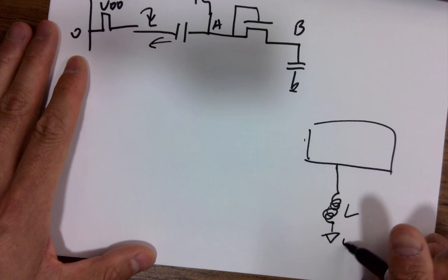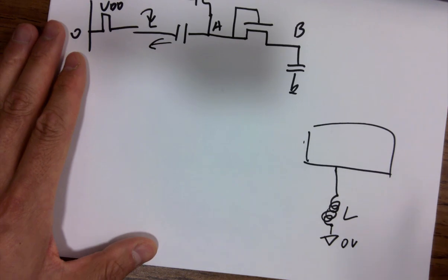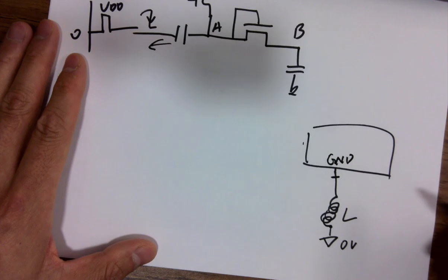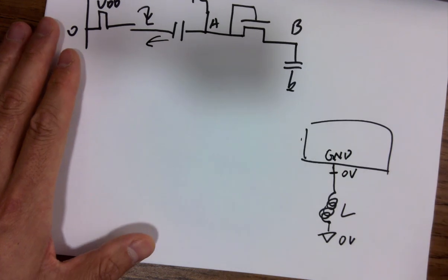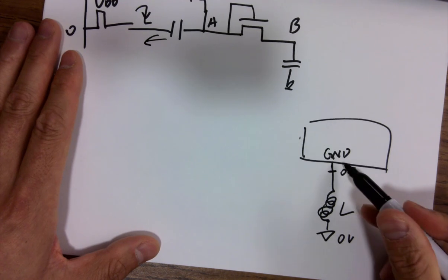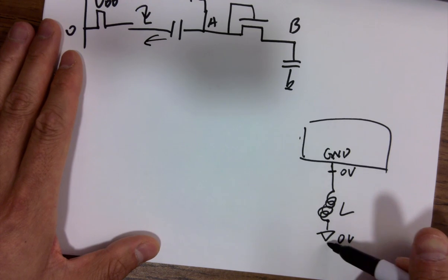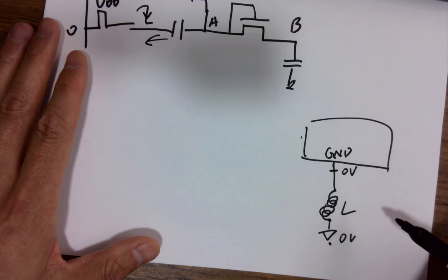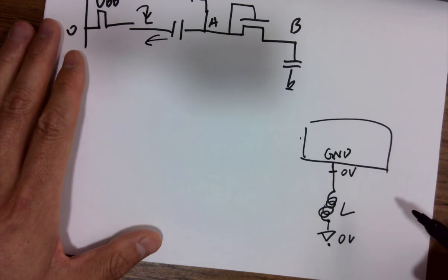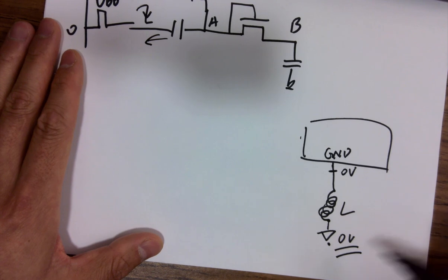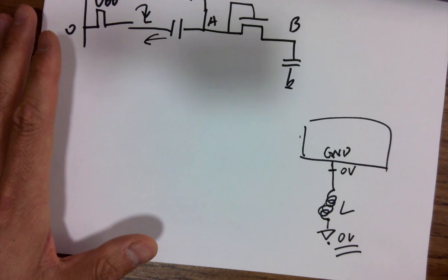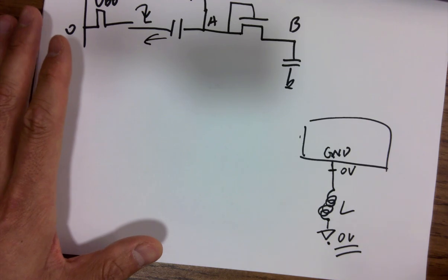So what is this one providing? 0 volts. Yeah? And you hope this one to be what? Steady 0 volts, right? And they place the inductor between the device ground pin and the real ground. You're thinking, hey, you're blocking the ground. Why do we do that? Is ground being affected? No. Why? Because it's DC. Even though it's 0 volts, it's DC.